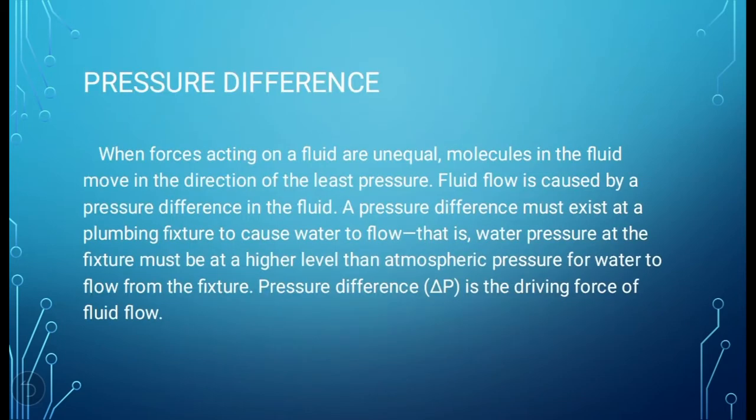Pressure difference. When forces acting on a fluid are unequal, molecules in the fluid move in the direction of the least pressure. Fluid flow is caused by a pressure difference in the fluid. A pressure difference must exist at a plumbing fixture to cause water to flow.